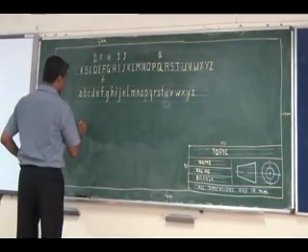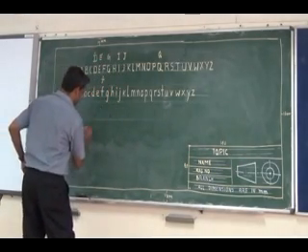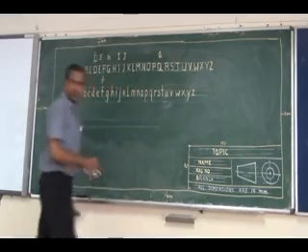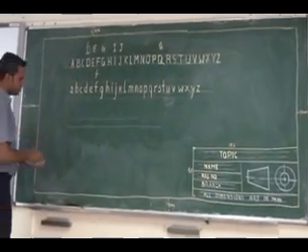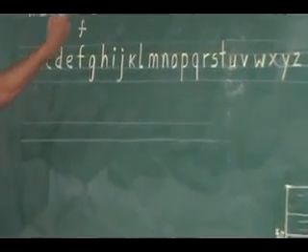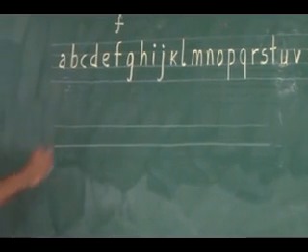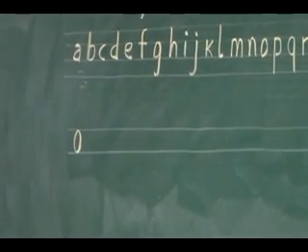Just you see that you write the numbers for 5 mm height. For parallel lines, the number will be 0. Starting from 0, 0 will be something like an oval. This is 0, this is not O, so there is a difference between O and 0.